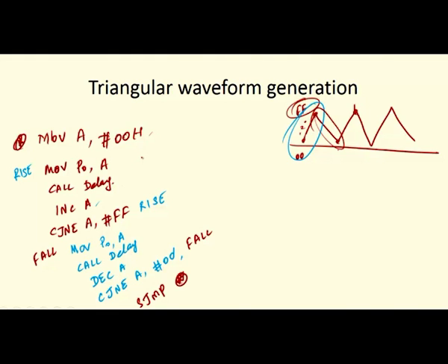Okay. So, the reason we give the delay is to get the proper frequency, so we are initializing the delay. Otherwise, it will get this kind of triangle waveform also. That is why we are initializing the delay. Suppose you want to initialize the delay for 1 millisecond, what will you do? 1 millisecond divided by 1.085 microsecond, already we have discussed. Based on that, I will get the value of 11, which is 8 bit only. So, I will take it as 256 minus 11, which is 245, and its corresponding hexa equivalent is F5.